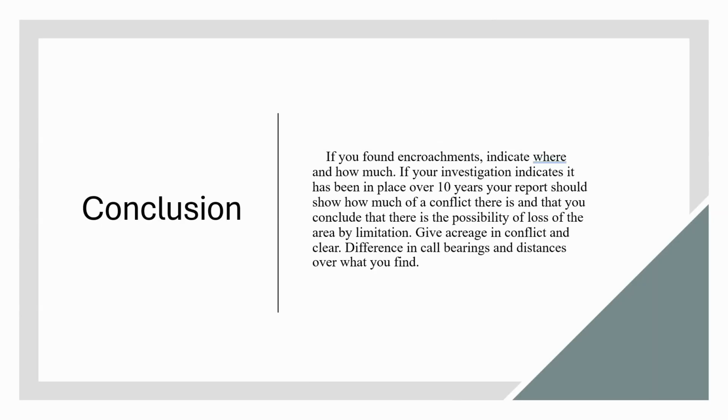So again, you found encroachments. Where were they? How much of an encroachment were they? If your investigation indicates it has been in place for over 10 years, your report's going to need to show that, because that's where adverse condition technically starts coming into play. Investors or potential buyers or developers need to know about this information, because there is a possibility of loss and limitation to their site.